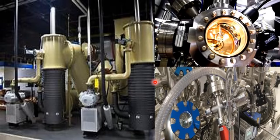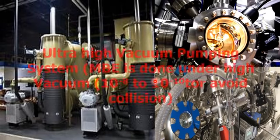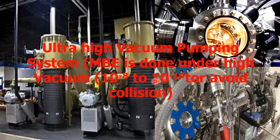Dear student, please note that I have also discussed at different points that the ultra high vacuum in molecular beam epitaxy is the heart of the technique, but it is also a disadvantage. The ultra high vacuum created in molecular beam epitaxy is somewhere around 10 raised to power minus 8 to 10 raised to power minus 10 torr.